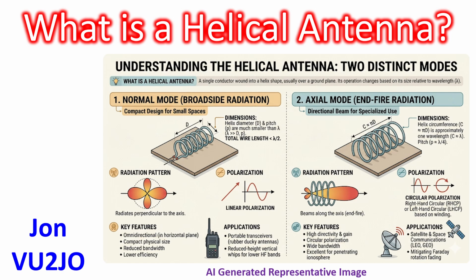A helical antenna is a specialized type of radio frequency antenna where the conducting wire is wound into the shape of a coil or helix, typically mounted over a flat reflecting ground plane. What makes the helical antenna unique is its versatility. Its electrical behavior changes drastically depending on the physical size of the coil relative to the wavelength of the signal it is handling. It operates in two primary, completely distinct modes.